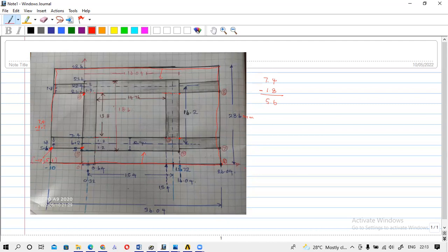If you give that position and give the appropriate length in the x direction and y direction, the x direction length is 10 millimeter, because we have taken this transmission line as 10 millimeter, and the y direction length is 1.8 millimeter. That is the width of the transmission line.